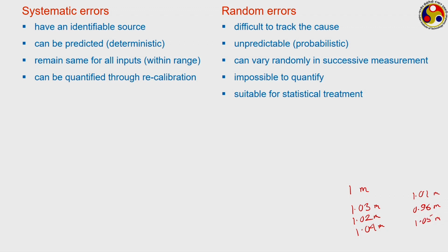Very difficult to compare successive values just from the magnitude, and so very difficult to get an idea about where the error is coming from. Whereas in this case, we can somehow guess that there probably is a problem with the zero bias, and we have to recalibrate the instrument to eliminate any kind of zero drift which may have appeared.